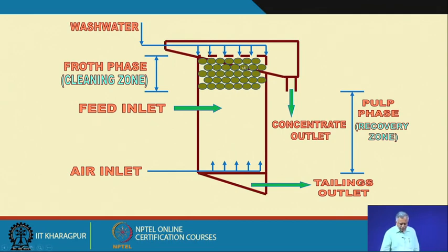An additional feature here is that you add additional water from the top, called the wash water. It helps in dislodging the entrained particles in between these bubbles, that means particles which may not be hydrophobic but are entrained in the void spaces between the bubbles, so that they can get dislodged.